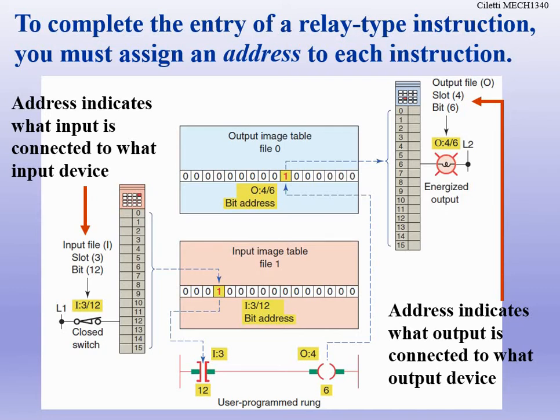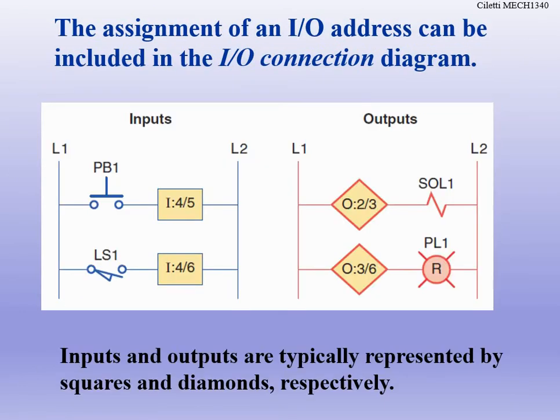Alright, so if you don't set your PLC up correctly when you're going to do your program, and you go write your program and you're like, oh, I'm using everything right, I'm using inputs, slots 0, 1, and 2, and I write my program, I'm using the correct outputs. But if you didn't set your PLC up correctly, your program's still not going to run, even though you're writing it the way you want and write it with the right inputs and outputs. Okay, so very, very important.